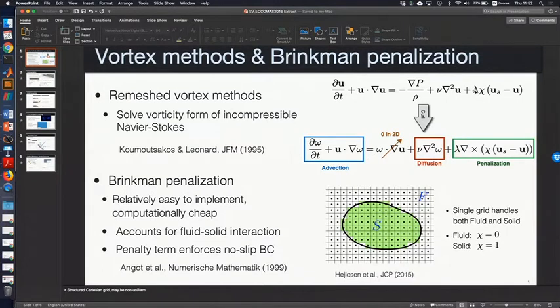Some people call this the DLM, discrete Lagrangian method. I forgot the full form. Different people have used different ones. I prefer using 1 over dt. And that's necessary to make the whole thing dimensionally consistent. See, this is velocity, velocity, chi has no dimensions. On the left side, we have velocity over time. So lambda equal 1 over dt makes sense.